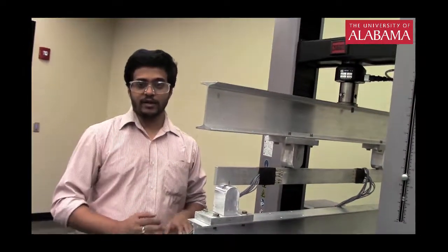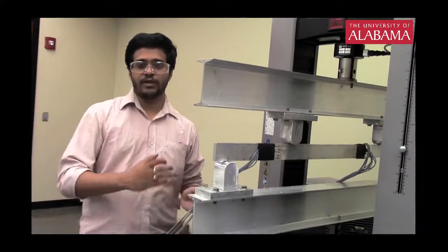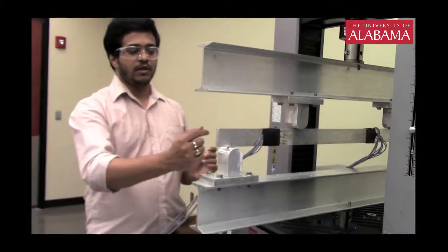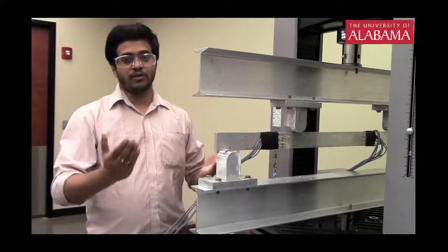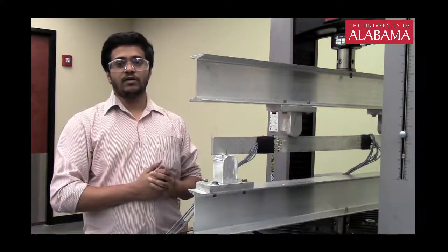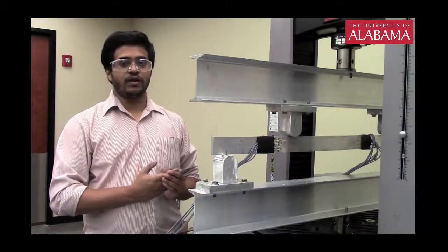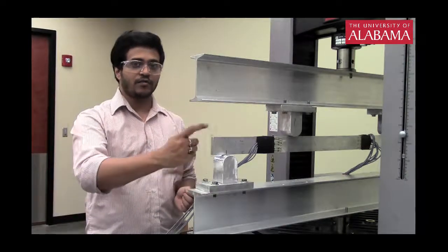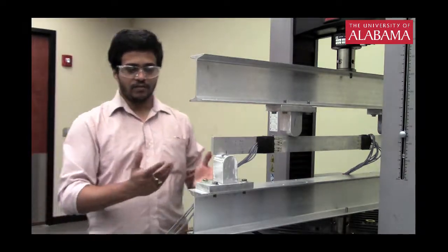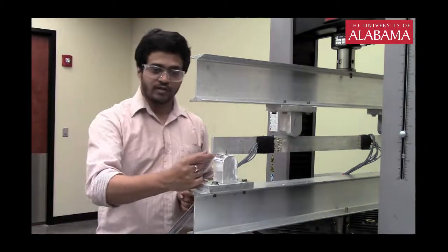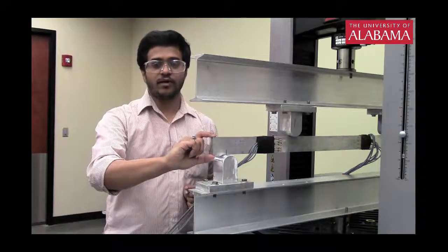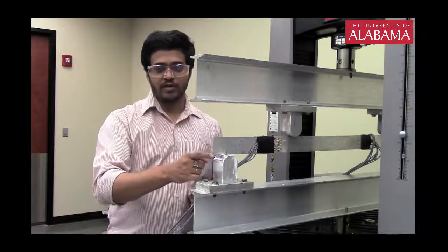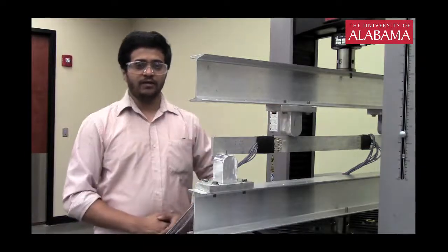Once you do that, the data collection for this experiment will be complete, and from the data we are going to plot the distribution of bending stress along the cross section, and we also want to find out the bending stress distribution from theory, from the geometrical configuration. One last thing before we end this video: don't forget to measure the cross section of the beam, because that is very important for your calculation. You need to know the dimensions of this cross section.